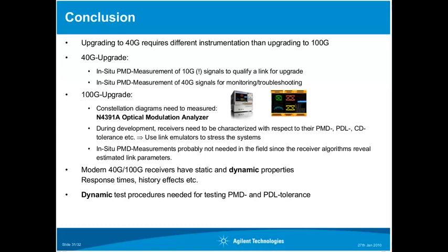What people normally characterize for an optical link is the average PMD, or the PMD coefficient. Let's say the PMD coefficient is 10 picoseconds. That is basically telling you what kind of variations of the differential group delay you will see. Assume your link has 10 picoseconds PMD. Then you can probably see 20 picoseconds, and sometimes 30 picoseconds, though 30 picoseconds is probably not so frequent.